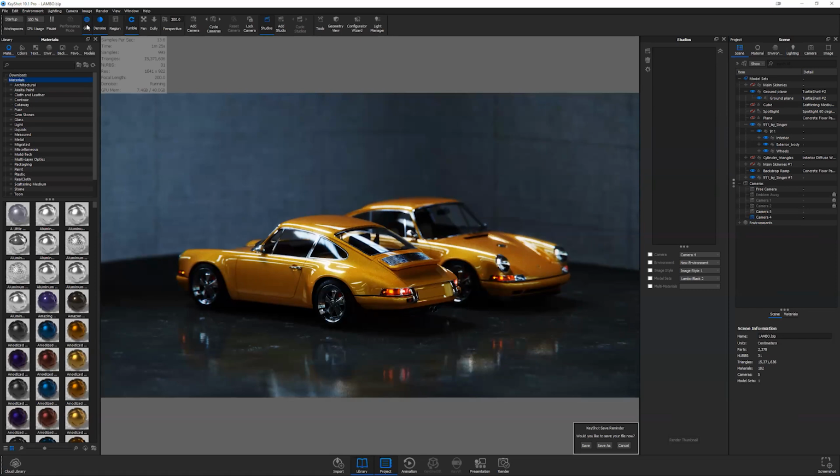We tend to have our own maps that we'll build out, and if it's a new product, we don't spend too much time doing UV unwrapping, particularly in KeyShot. If we need it, we sometimes use some procedural stuff in Blender and output those maps and apply them in KeyShot, just because that's our steady workflow. I know KeyShot has an easier to use interface, but we found that we're just able to use those maps and apply. I guess that's just our workflow at the moment. That's the way we've optimized it anyway.